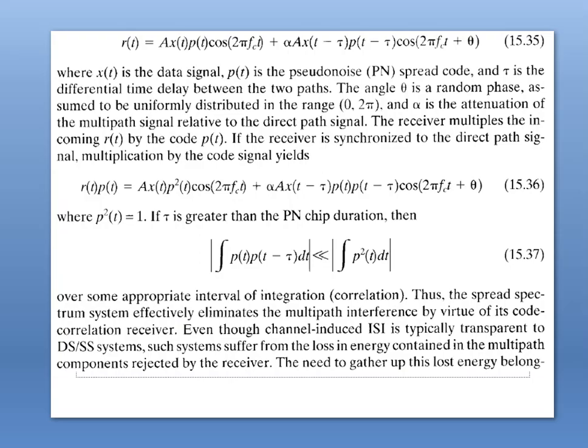Earlier we described a channel that could be classified as flat fading, but occasionally exhibits frequency selective distortion when the null of the channel's frequency transfer function occurs at the center of the signal band. The use of a direct spread spectrum sequence is a practical way of mitigating such distortions because wideband spread spectrum signals can span many lobes of the frequency selective fading channel's frequency response.